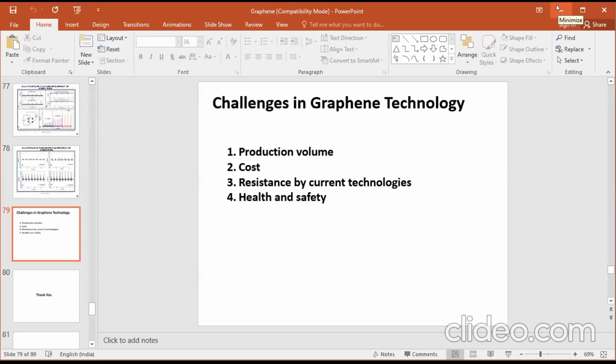Like that, in different applications, for example, aluminium also we can add graphene. We have done that type of work also, but we can add only up to a certain percentage. The problem is that if you add more graphene, what we have found is that the metallic nature, the drawability of the material, will be lost. The material will become brittle. So a maximum of 1% is actually advised. But you can play with the material. So definitely it is possible.